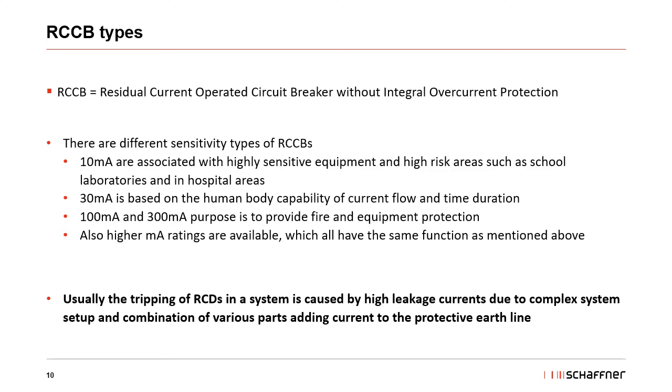In addition to these complex systems, if we integrate EMI or RFI filters in the system, the leakage current is also rising for the whole system because the EMI filters will also add additional leakage current due to the Y capacitors to the system. And yeah, this might get your RCCB tripping every time you switch on the machine. And this needs to be reviewed before you connect the machine to the grid or before you try to find the right RCCB for your application.